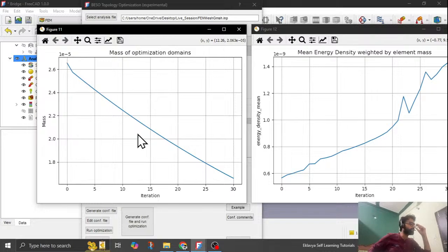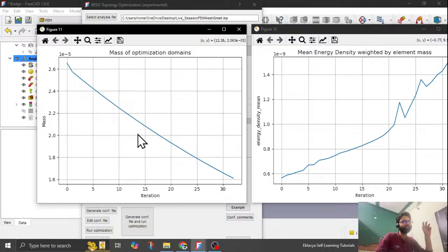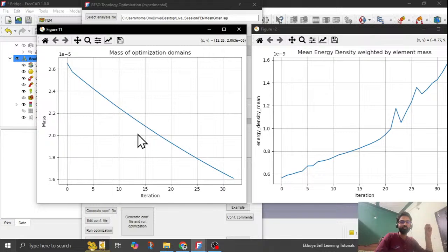Yeah, so I was saying the live went very well, but eventually I was not able to figure out what's happening. Maybe my analysis is wrong, or maybe some constraint is wrong, right? I was just trying to revisit everything. Eventually it was the directory spacing issue. The space should not be there in the folder names or file names, and as I mentioned earlier, in a folder name called live session there was a space, and this macro faces issues in case spaces are there.